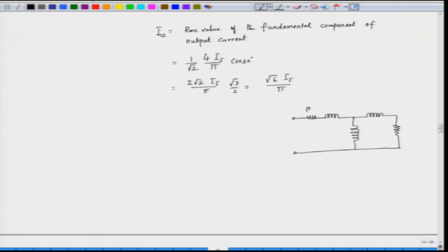So, this is the stator resistance, the stator leakage reactance, the rotor leakage reactance, the rotor resistance referred from the primary side and the magnetizing reactance, and here we do not have any voltage source, but we have a current source. The current source has the RMS value I_S ampere. The rotor current here is I_R and the current in the magnetizing branch is I_M. Now, this is our equivalent circuit, we have a current source here.